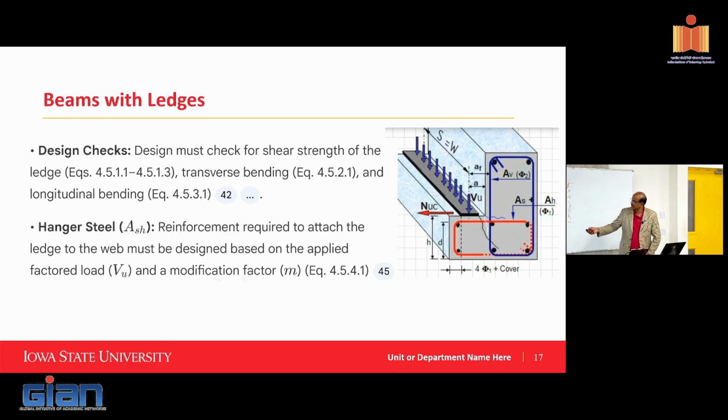This steel will be there in the standard document, but it will not be meeting the load that you're planning to apply. So that's why you need to check. Picking the standardized section is one step. Doing the design of each and every component is basically checking to make sure they will be satisfied for your case, as well as providing additional steel as needed to avoid that.